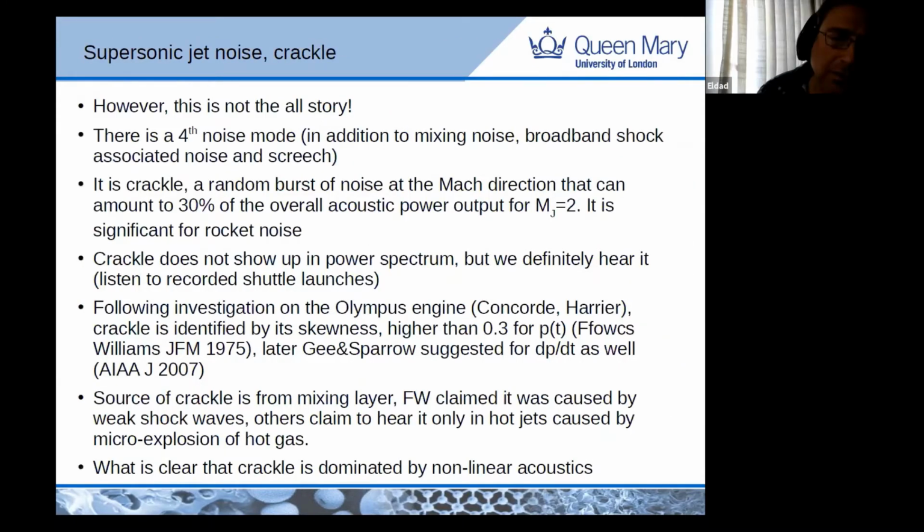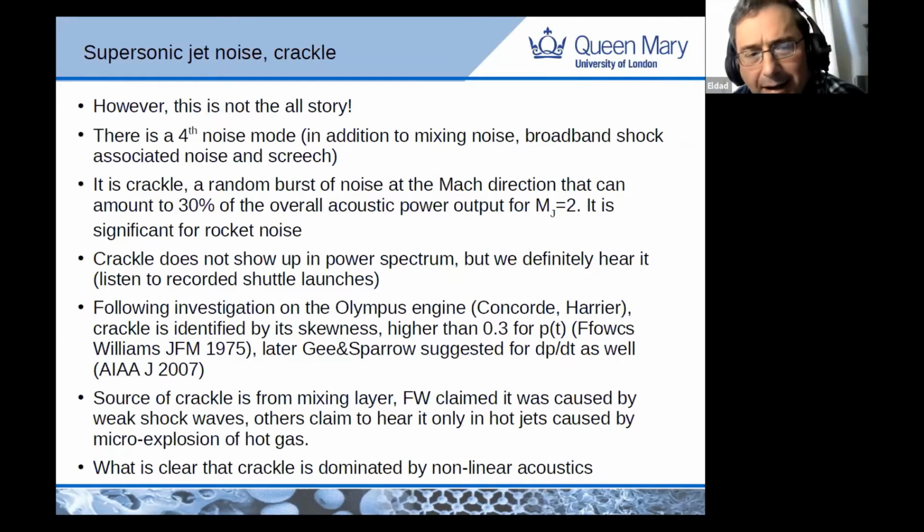However, this is not all the story, and this is what I wanted to talk more about today, and that is crackle. Crackle is a random burst of noise, more or less in the Mach direction, but it's not the Mach wave itself. It can amount to about 30% of the overall acoustic power. And the problem with crackle is that it doesn't really show up in the power spectrum. We definitely can hear it.